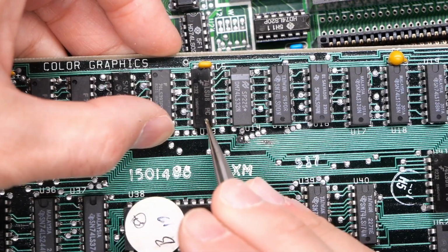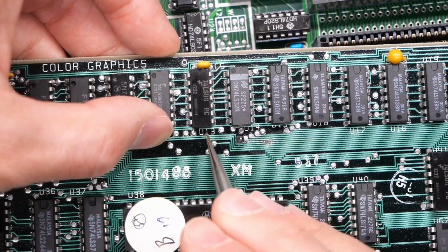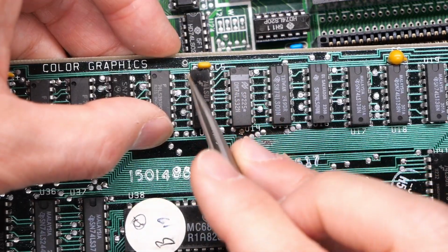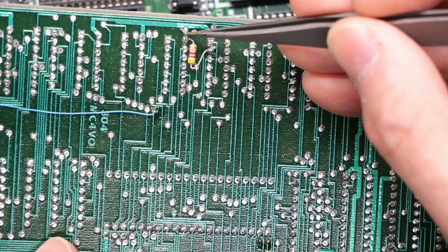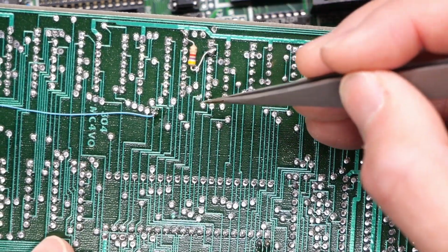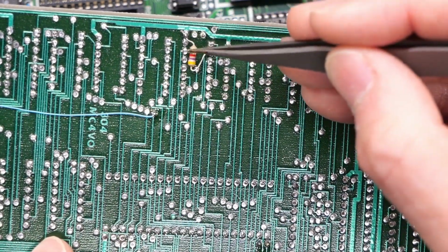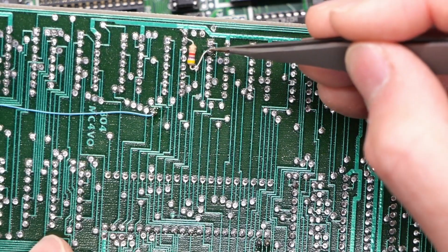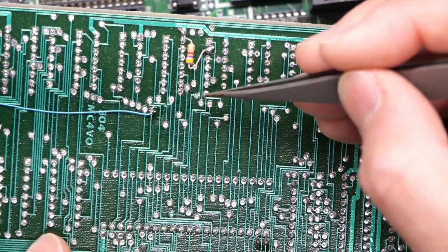Now the actual chip we installed that resistor onto the back of is U13. So if you just want to make sure you're in the right spot, you look for U13 and then you go to the back side and you install the resistor and cut that trace. If I restore this trace here and I even leave this resistor in place, it'll be fine actually, to be honest. That will restore the original functionality.